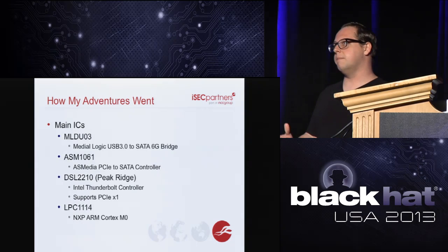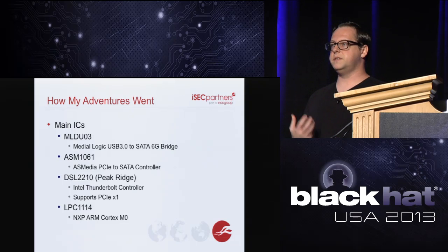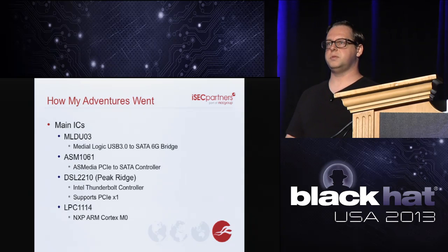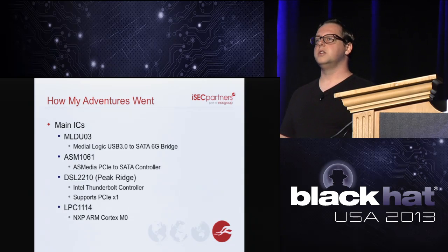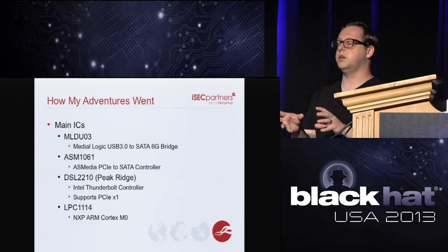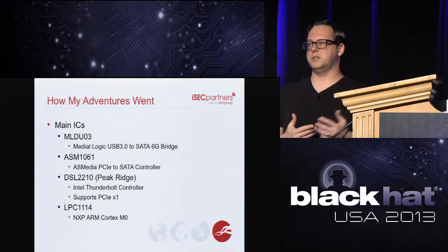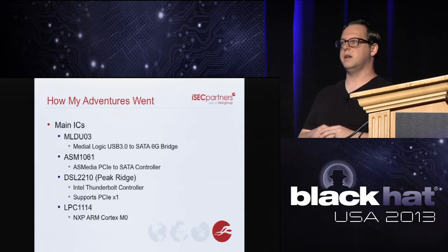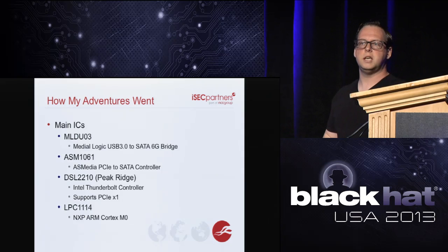And so just thinking about this as a hard drive, we know we're going to have SATA connecting to our hard drive. We have USB 3 and Thunderbolt as the input. So now looking at the chips, we have a USB 3 to SATA controller. So we start building our two paths, one for USB 3 down to SATA and one for Thunderbolt down to SATA. And this chip kind of solves that mystery. It's USB 3 to controller, controller to SATA. We're done. So that leg is pretty much taken care of with that chip.